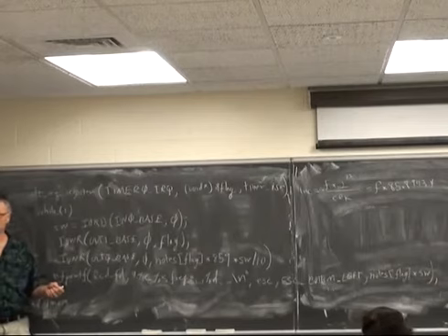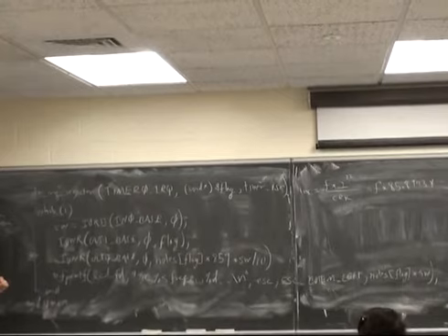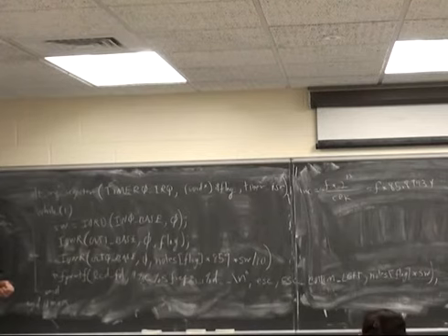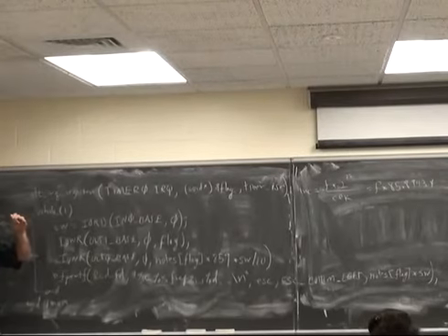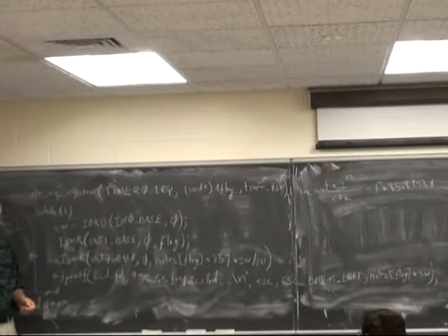There's going to be a NiosII, which is the master node for all of the iterators that you're going to build. Unless, of course, what you want to do is you want to have multiple Nios. You can define multiple Nios CPUs. You just append them to the bus in SOPC Builder. You get a module out that includes the interface to all of the CPUs. One module gives you the interface to all of the CPUs. You connect the CPUs to whatever outside stuff you want, and then you write separate programs to execute on each different CPU.